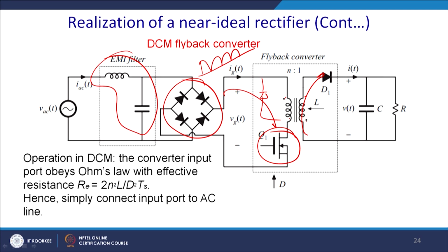It is an oversimplified circuit. Then the current will flow back to the secondary. You can choose the turns ratio freely, because you have to have a huge drop in voltage for the mobile or the laptop charger, and thereafter you can also change it by the duty cycle.